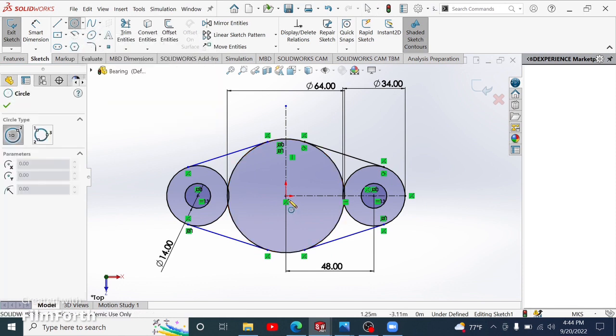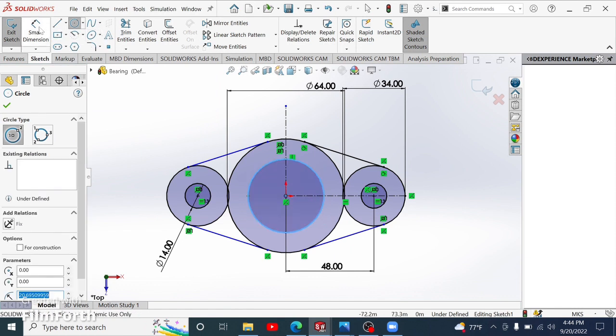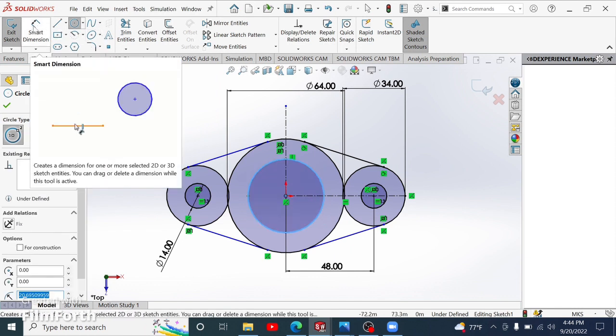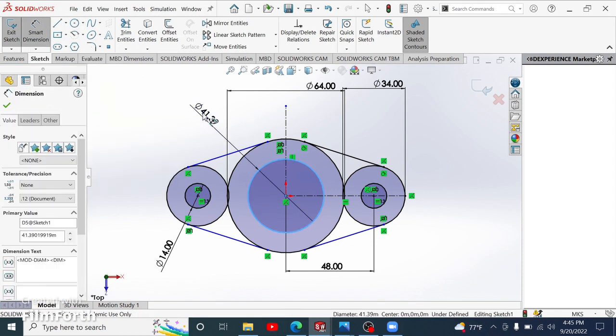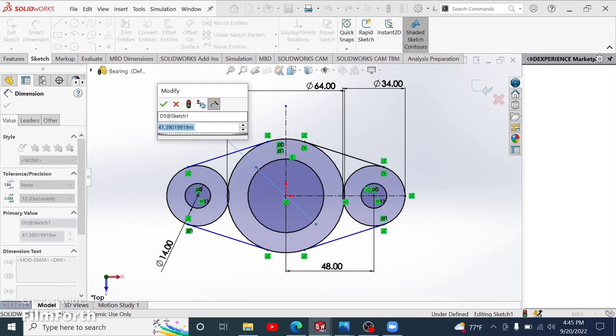I'm going to click on my circle again, add in the center. And then from that one, I need to add in my dimension. On this one, there's 2 different tolerances. That one, we'll learn along the way, because on here it says 2 different types of tolerances. 41.28 all the way up to 41.17. The reason it has those 2 is that, in the term, it's called general dimension and tolerance. It means that most of these components have to be shaped specifically within that tolerance.